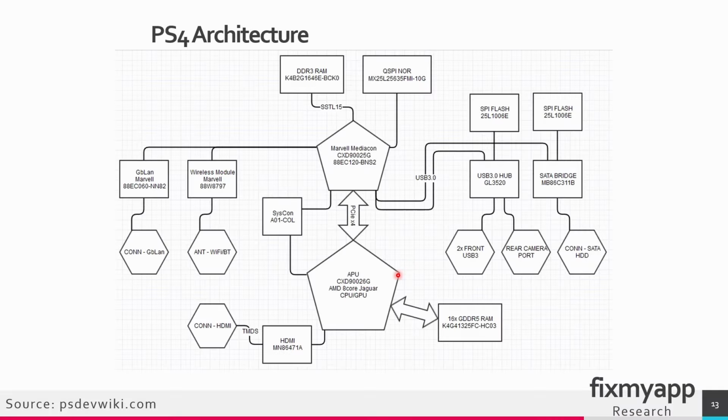When you have a blue light of death, most of the time the problem is in this area. So the problem could be a bad APU, the HDMI circuit, or the GDDR5 RAM modules. So if something in this circuit is not working, you get the blue light of death. Also, if the NOR IC is faulty or the firmware is corrupted, you also get the blue light of death. When only the HDMI circuit is faulty, most of the time you get the white light of death.